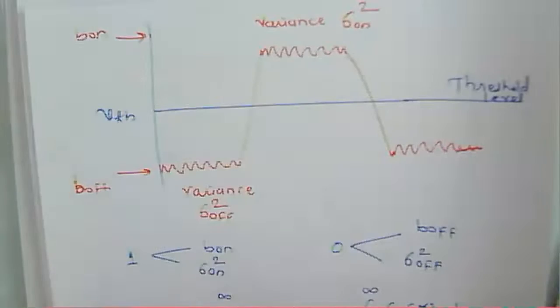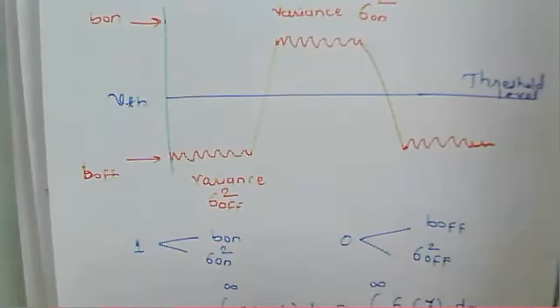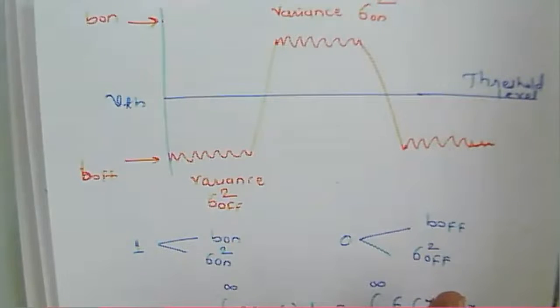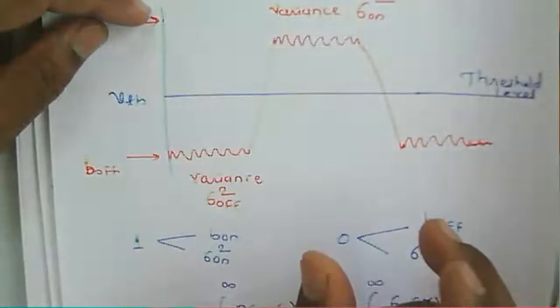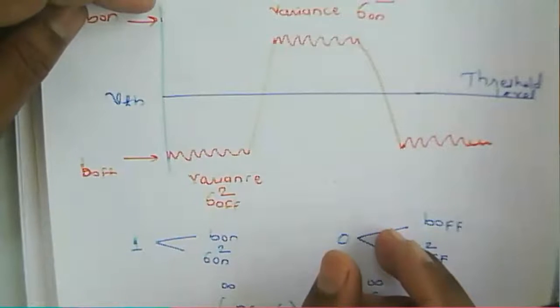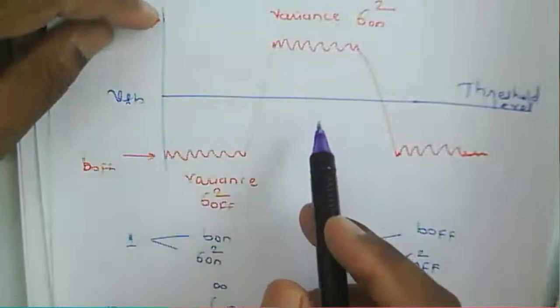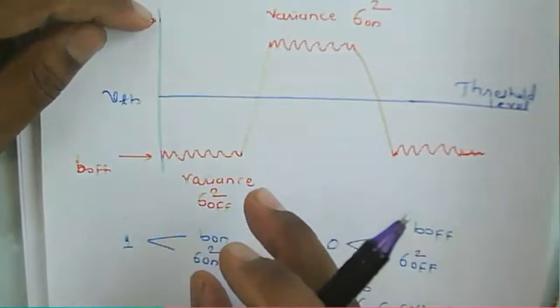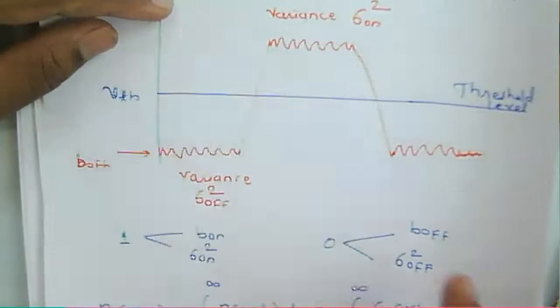So means the performance of a receiver, we can say that it is defined for a transmission link. When we design a transmission link, then the performance of a receiver depends upon the bit error ratio, and that bit error ratio is again depending upon the threshold value or threshold level in which we can obtain the signal to noise ratio.